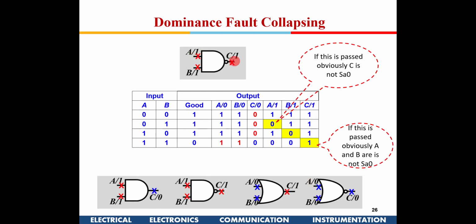So if I go to a NAND gate, similarly, if I make a table for this and you try to analyze these things, I'll share this PDF with you. You can do this analysis. So finally, this is what you need to remember. For an AND gate, these 3 tests will be good enough. Stuck at 1 here, stuck at 1 here, stuck at 0, right? Because these stuck at 0s equivalence is here, right? And for stuck at 1 here, these are dominating. So this has come here, right? So similarly here, red indicates dominating.